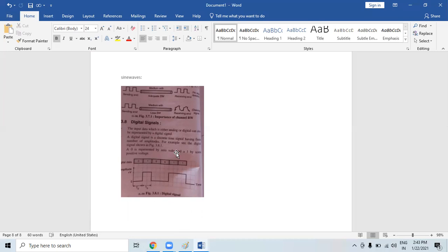All efforts should be made to reduce the required channel bandwidth so that we can fit more channels in the same available spectrum. The bandwidth of the medium, also called the channel bandwidth, is defined as the maximum frequency it can allow to pass through it without distorting the shape of the signal. If the medium has less bandwidth than required, then signal distortion will take place.